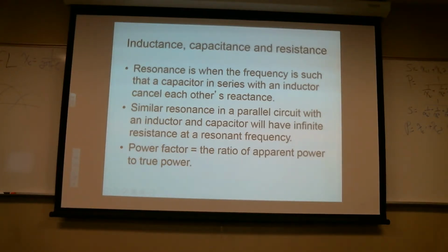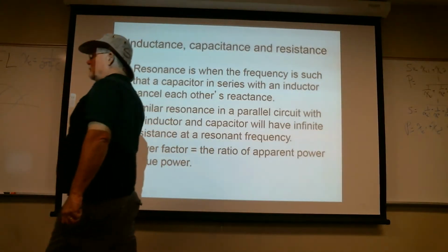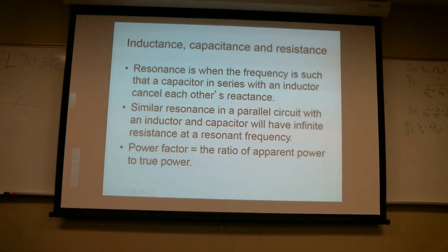Put it in terms of dollars. For every 89 cents you spend on power to power this building, you're also paying 11 cents for nothing. Well, after enough 11 cents, pretty soon you can say, maybe I could buy a couple of capacitors and reduce that. So I could pay for some systems to accommodate that.